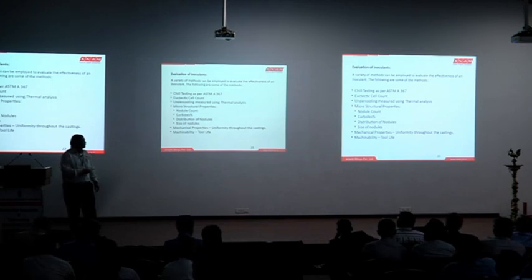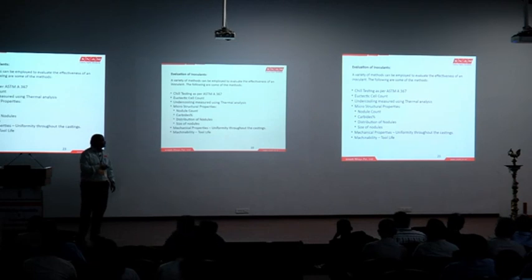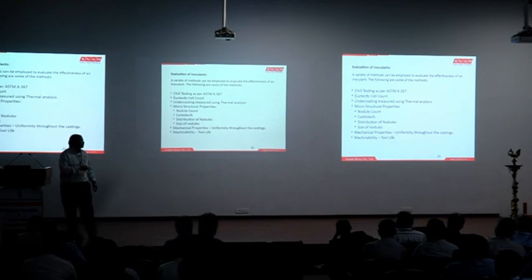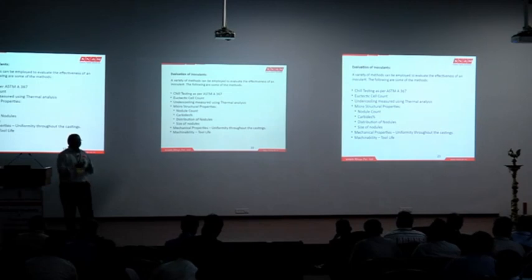Microstructural properties are the final responses that a customer relates to his end properties, say for example, strength, yield strength, low temperature impact resistance. So all are related to the microstructural entities. Nodule count, everybody expects zero carbides, or if allowed, within the workable range. Nodule count or type of graphite flakes and amount of graphite flakes. Distribution of nodules, the size of nodules, in the same way in grey casting, distribution of graphite flakes, type of graphite flakes and the amount of graphite flakes.